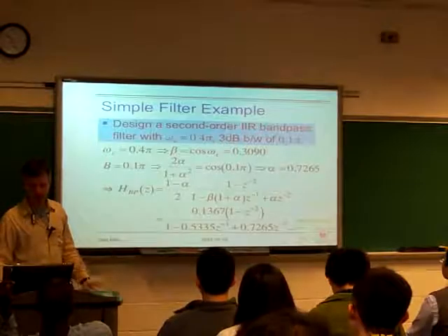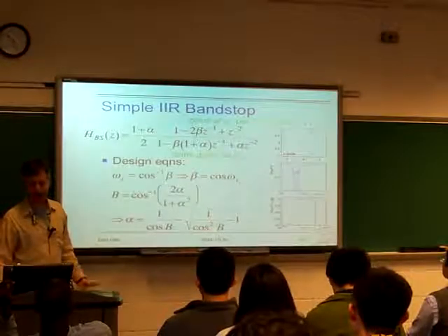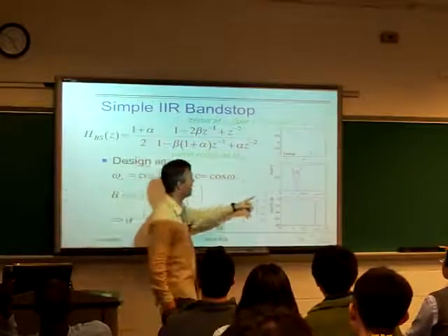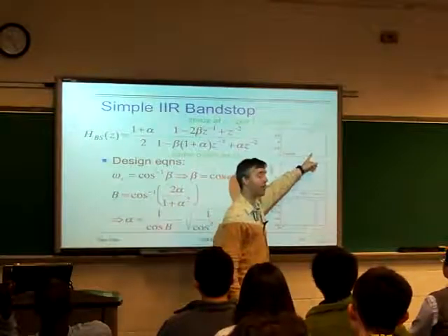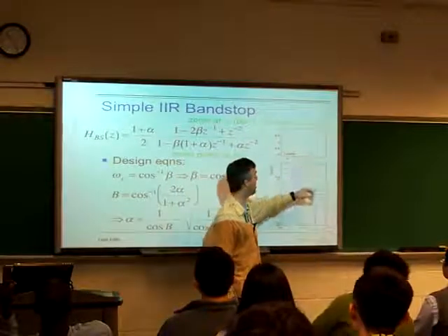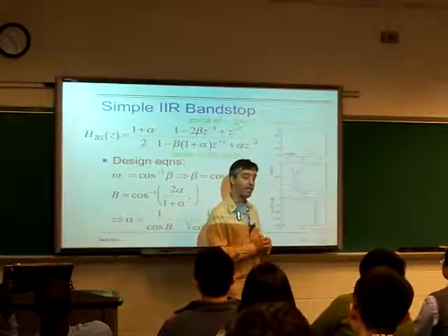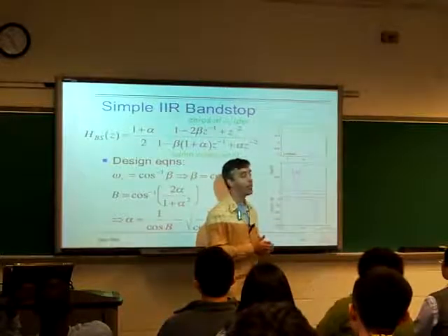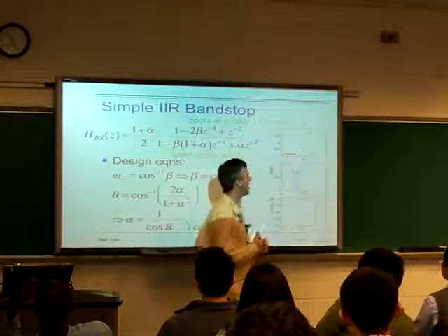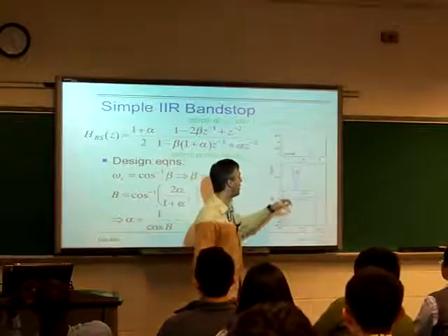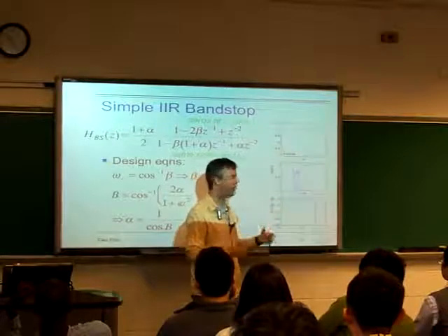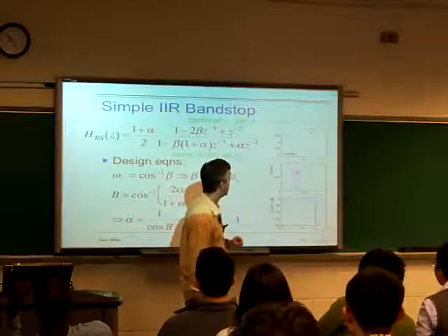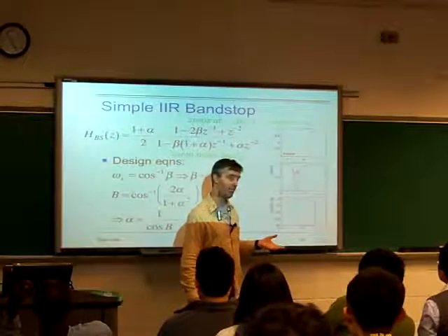But there are many more complicated filters we can look at, which we'll see as we move forward. The band stop filter, by putting a 0 exactly on a frequency, you can, in theory, completely eliminate it. Of course, a single frequency is an idealized concept because it means a sinusoid that is constant amplitude for all time. But as we've spoken about the effects of transients, ignoring those, you can completely remove a single frequency with one of these notch filters, and that's tremendously useful.